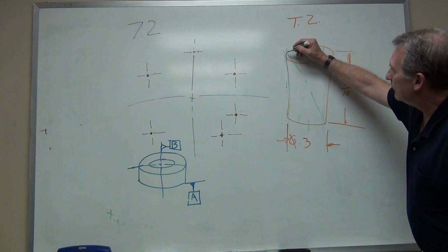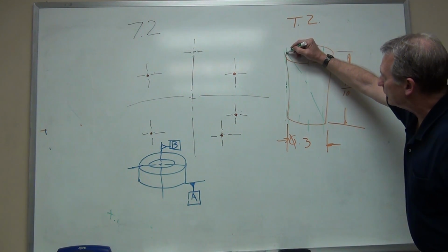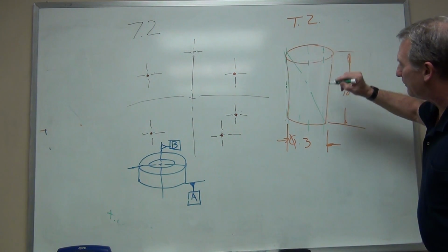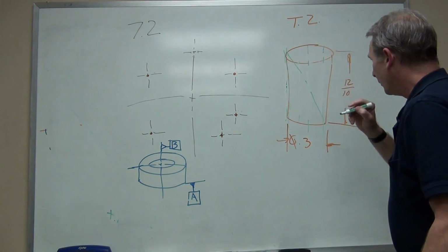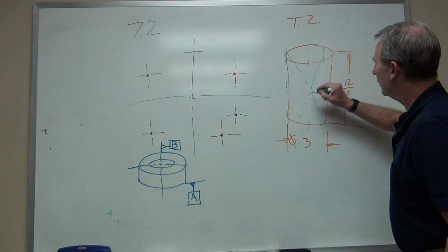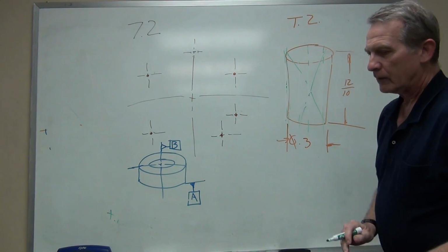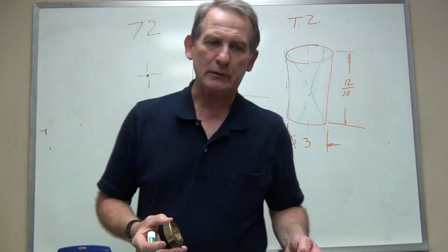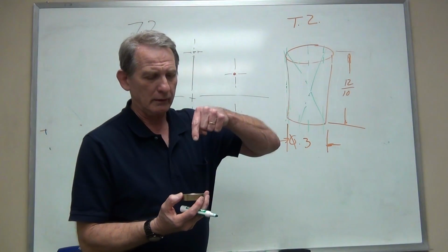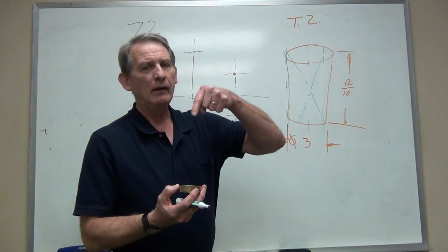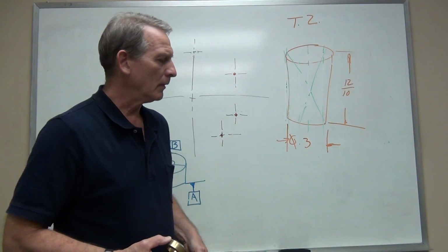And it can be tipped as badly as touching the tolerance zone here at the top and touching the opposite side on the bottom, or anything in between. Anything else goes for orientation. So in this instance, the tolerance zone is controlling the translation and the orientation.